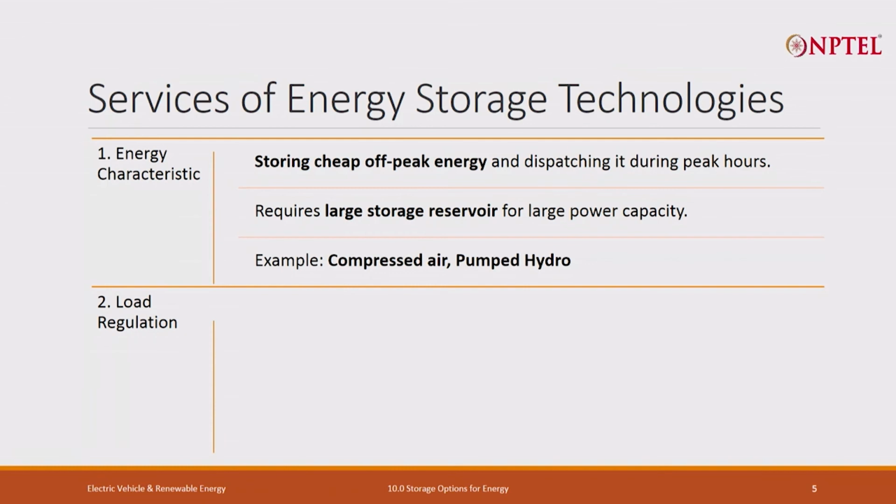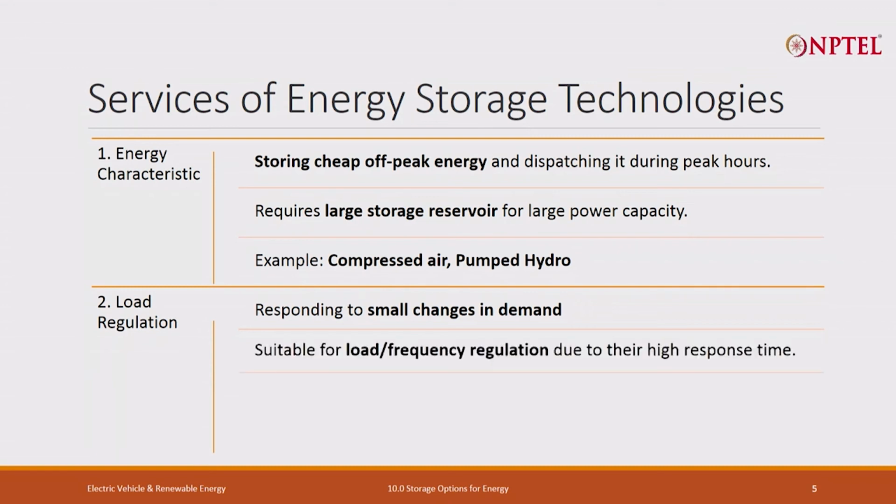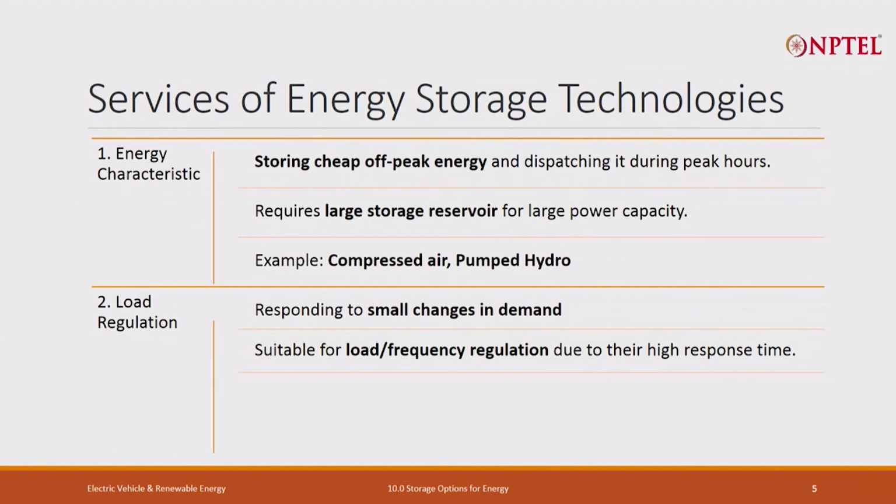Examples: compressed air, pumped hydro, hydroelectric power plants. We are also thinking about metal air batteries like zinc air, aluminum air. The second one is load regulation. It's a very important part. It means responding to small changes in the load, changes in the demand. Otherwise, your frequency starts changing and then the grid trips, because grids work only between certain frequencies. It's suitable for load or frequency regulation because of very high response time. You need to immediately pump energy. Otherwise, if the grid trips, then everything else would be a problem.